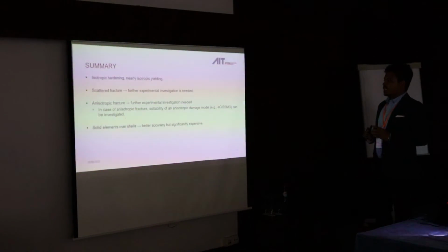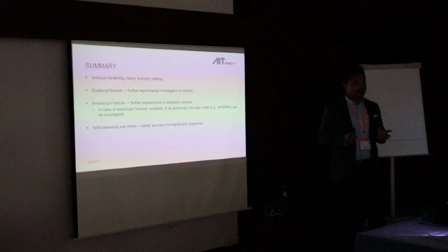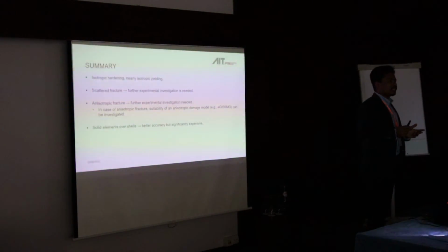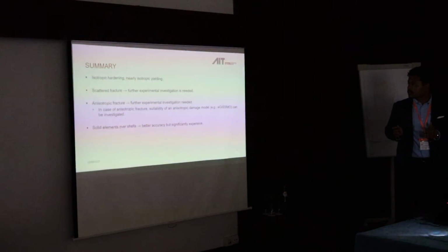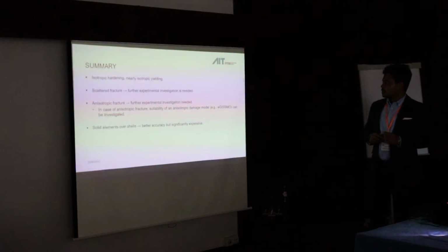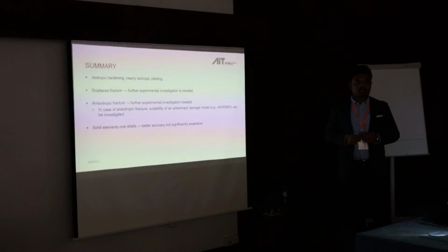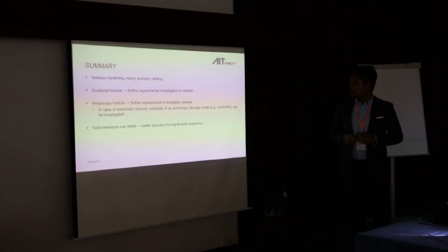We have an indication of anisotropic fracture, but only under uniaxial tension load. If we want to make a whole experimental characterization, then we have to repeat all those shear notched biaxial tests in all three directions and see how it behaves. And in case it really shows an anisotropic fracture, then we cannot use this isotropic damage model GISSMO. There is a model already implemented in LS-DYNA called eGISSMO, which considers the directions,